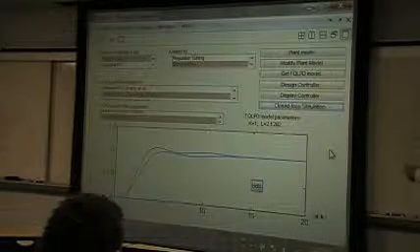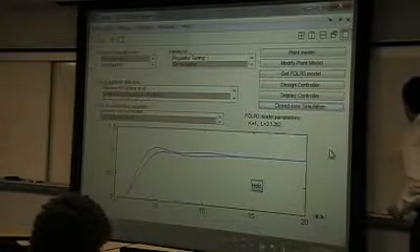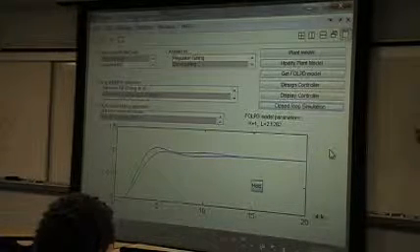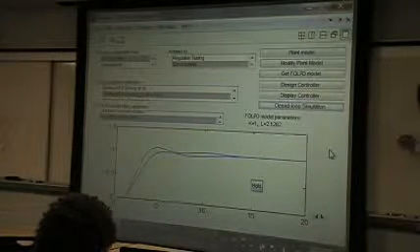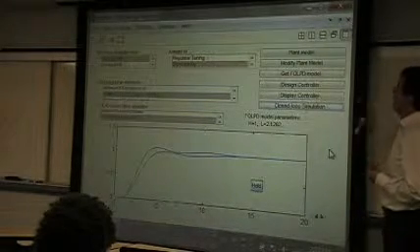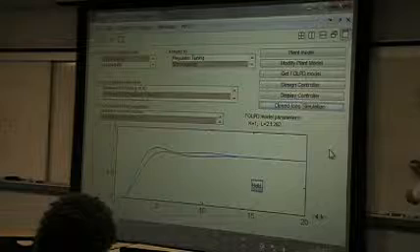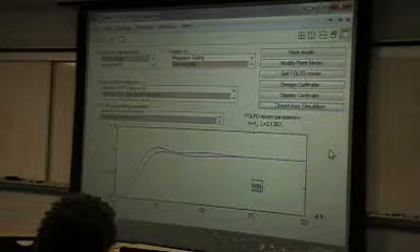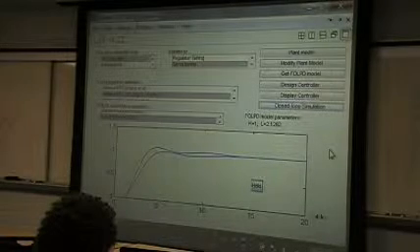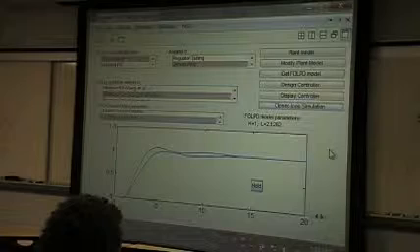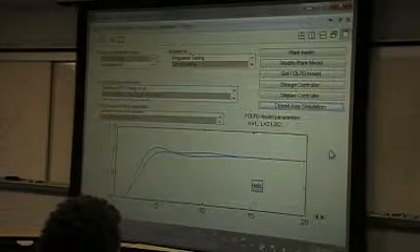If the step response of the plant model is something like this, or even if there are oscillations, you can get K, L, T. If it is something like this, then you cannot design a controller using this algorithm. You have to use something else for this kind of plant. You have to search for design tuning rules. I think the handbook has another kind of tuning rules.